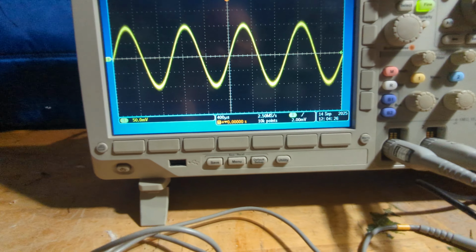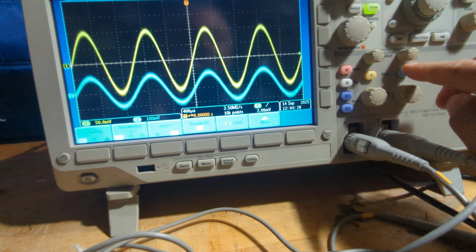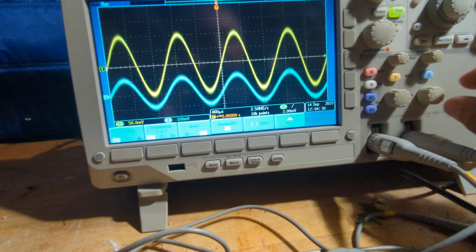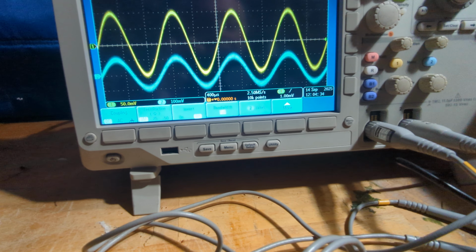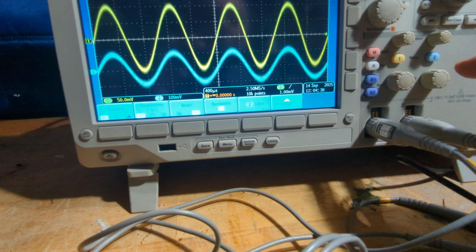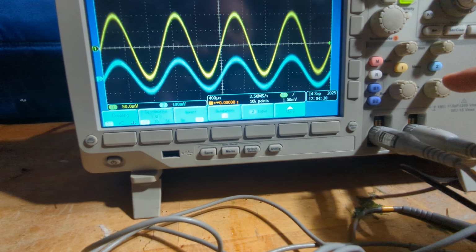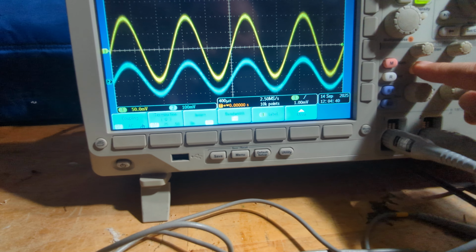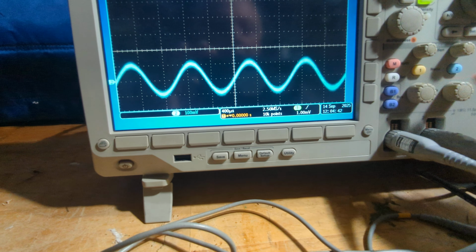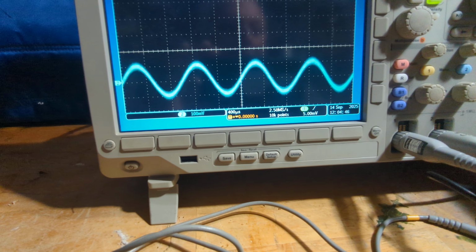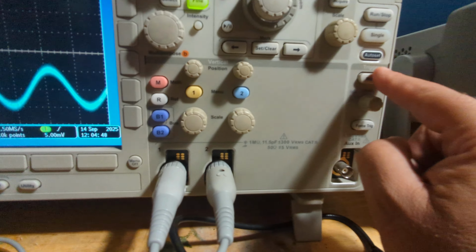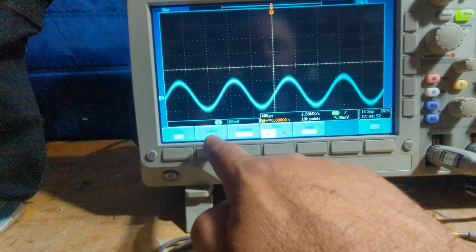And so if you don't intersect that waveform, it won't work. We can turn on signal 2, and since it's the same signal, it should be triggered. I'm going to turn off channel 2 and press the trigger menu, and it's saying that it's source 1.